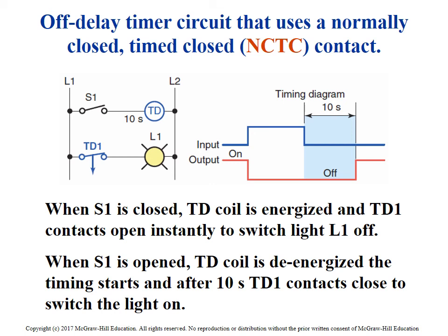So normally closed timer contact here. Again, same idea. We come in, we see this guy come on, so it actually goes from an on state to an off state because it's open. It opens because it's normally closed, and it stays open until it reaches the timer done. At that point, it turns on.